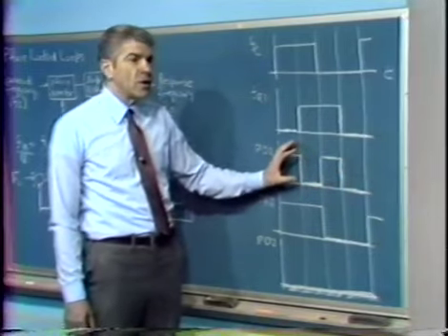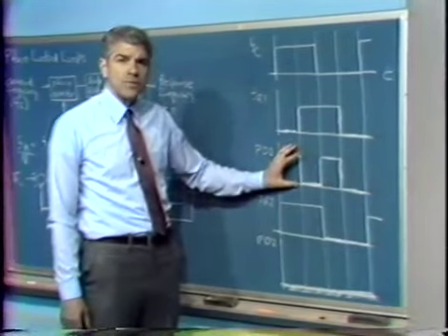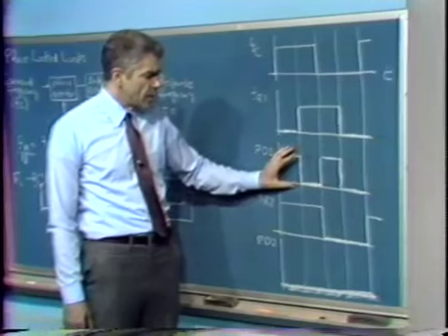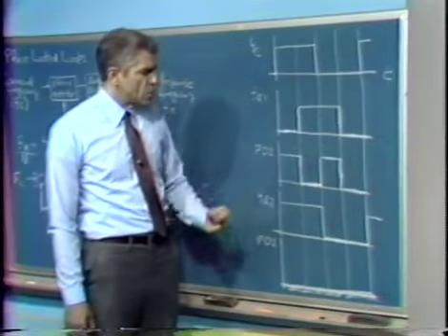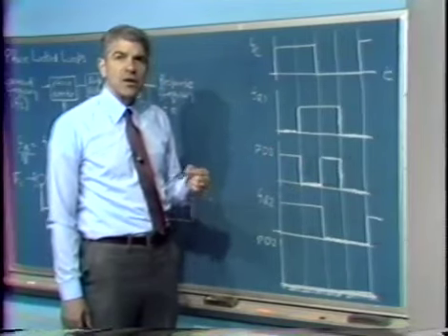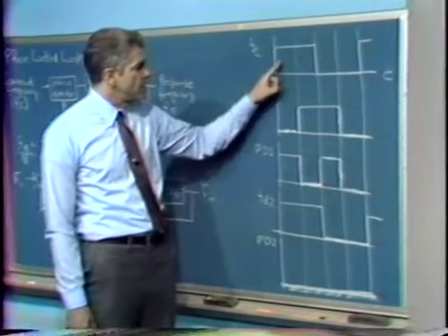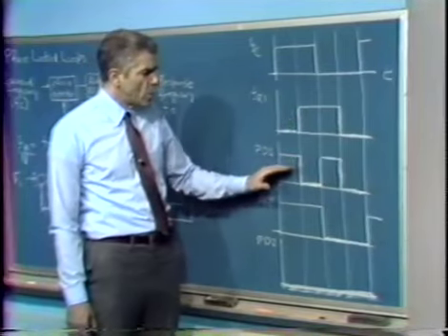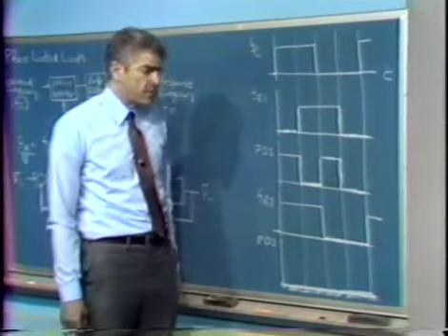There's some sampling going on. We have sampling kinds of problems here, and that puts a very real limit on the crossover frequency of the loop. And as we did in the case of the oscillator whose amplitude was controlled, we argued that to eliminate those sorts of problems, we cross over in this kind of a loop at a very small fraction of the operating frequency. Here, we intend to cross over at a small fraction of f sub c or f sub r. And by doing that, we're able to easily extract the average value of this signal to use as a phase